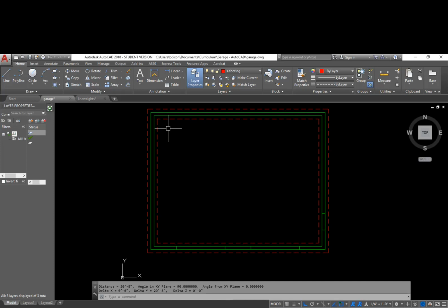So the rule of thumb for laying out cut joints is if I have any supports in the middle, I want to isolate those and have my control joints or my cut joints go away from any supports like columns in the middle. Since we don't have anything in the middle, the next rule that we have to adhere to is a 20-foot maximum span for the concrete.